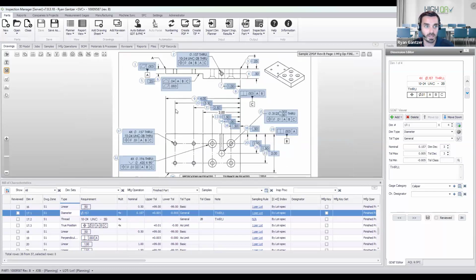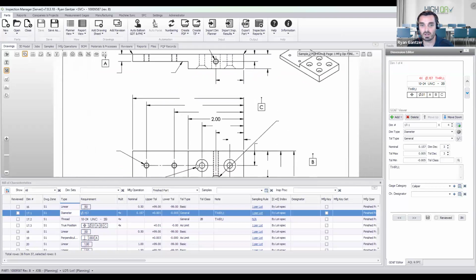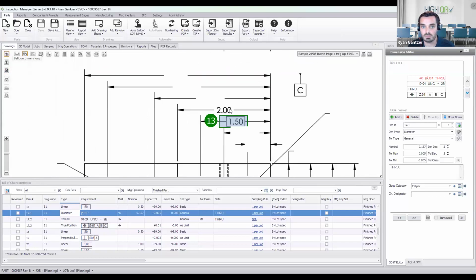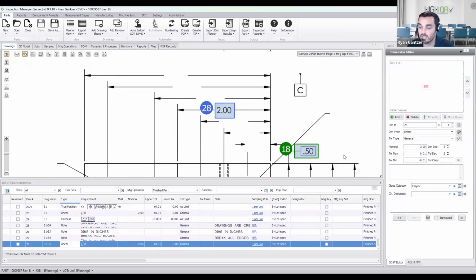Another efficiency tool we have is called whiteout balloons, top left. Once I click that, it hides everything that's been captured already. So as you get more complex drawings, it's just an easy way to see if anything has been missed. And you can then zoom in and just box select. It is a recommended best practice to double check what the system comes up with. Right-hand side of the screen, right? Peek into the database.